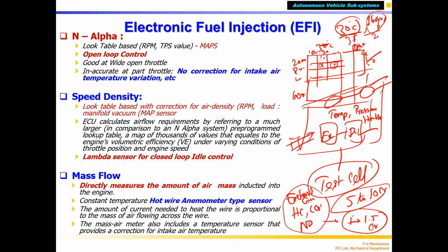Say, for example, 0.8 bar. Not 2 bar, because pressure is not going to increase on the earth. As you go up it reduces, but suppose your vehicle goes into deep valleys, where the depth is lower than sea level, the pressure can become 1.1 bar, something like that. Mining equipment, correct? Gold mines are 1 kilometer deep, and there you have excavators run by diesel. You create a map; a diesel engine also needs a fuel injection map like a petrol engine, open loop control.